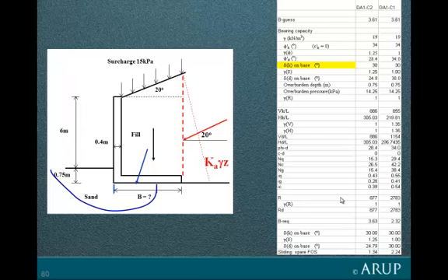I just point out here that pad foundations, spread foundations, may well be not for structural pads, but for the base of a retaining structure. And here, of course, we do get eccentricity of loading, inclination of loading becoming important, and those will start to affect the values of the bearing capacity factors. You can see over here, inclination factors in particular for inclined loads can halve the bearing capacity quite readily. This wasn't properly spelt out in BS 8002. I think it's a much clearer presentation in Eurocode 7.